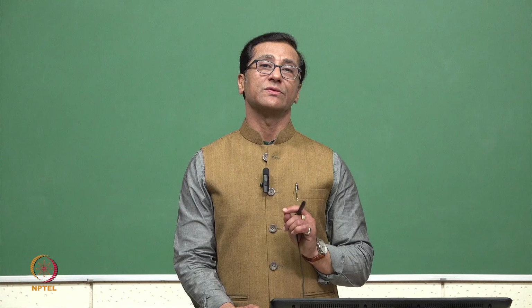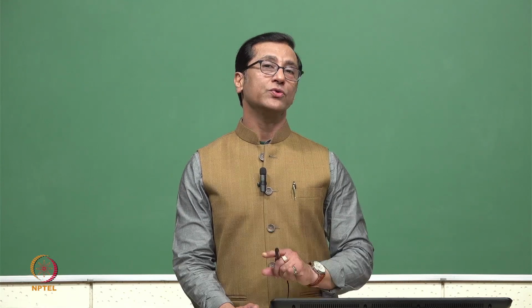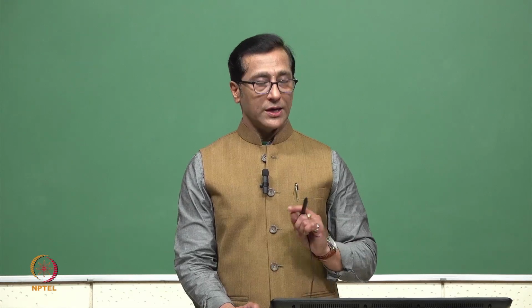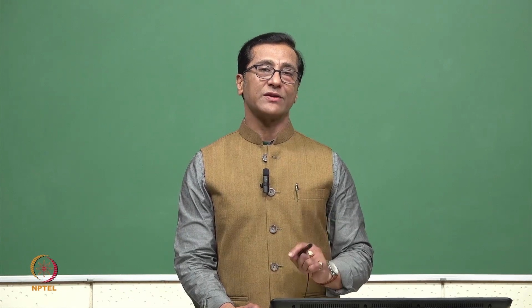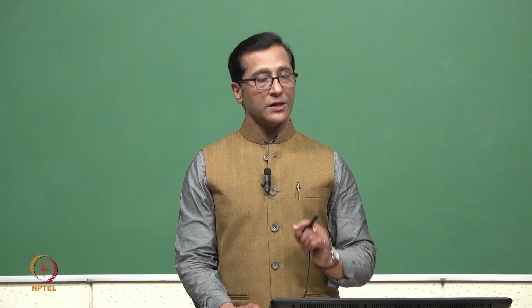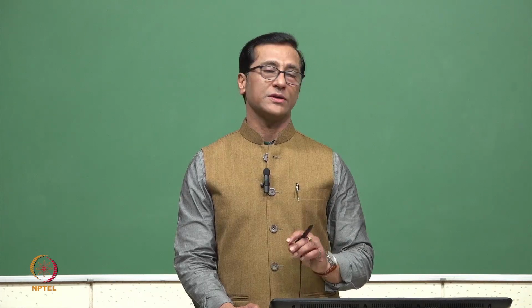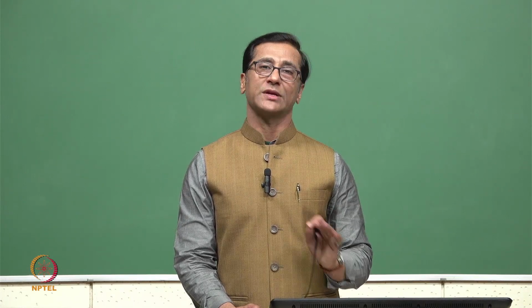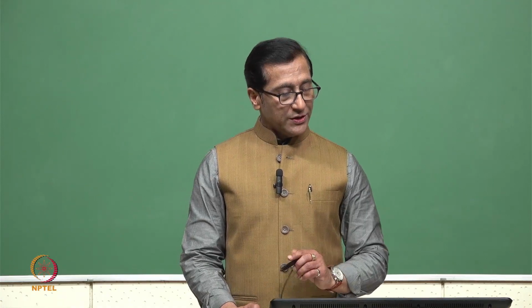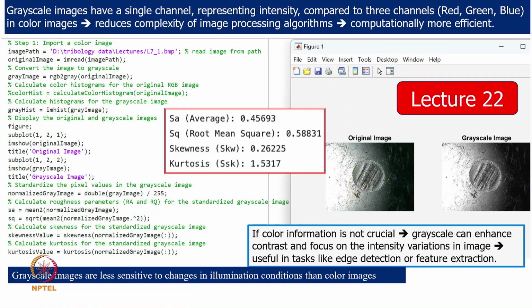If it is, then we need to account for two volumes, not one volume. However, most of the time the bearing is a sacrificial material. The bearing wear will be dominating and journal wear will be almost negligible. Now, this is what we have done by measurement of the wear.